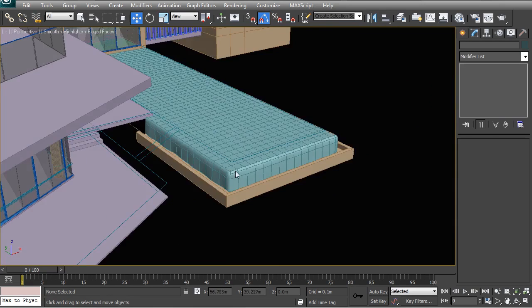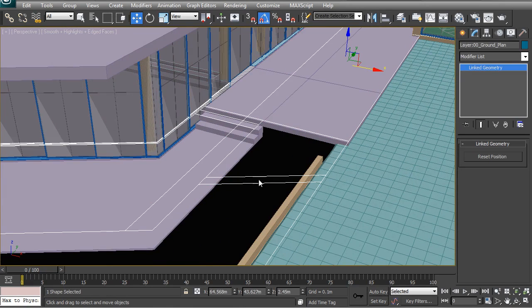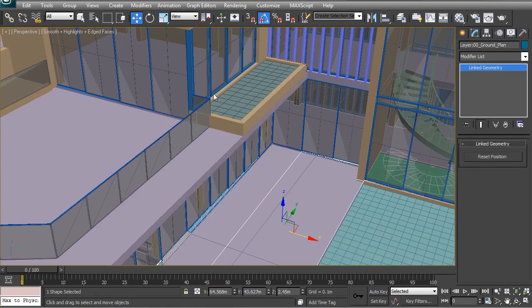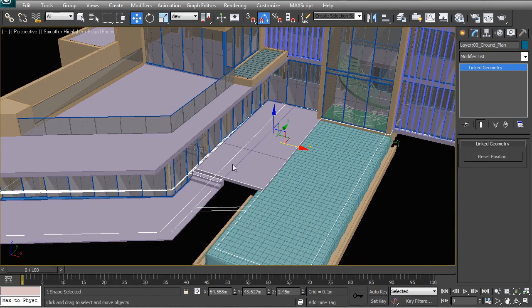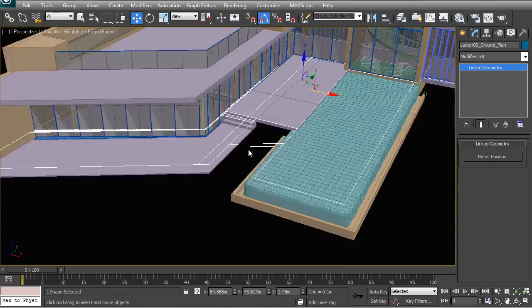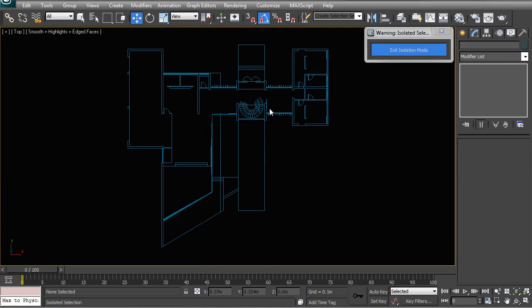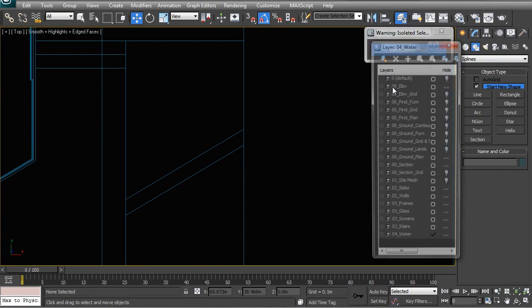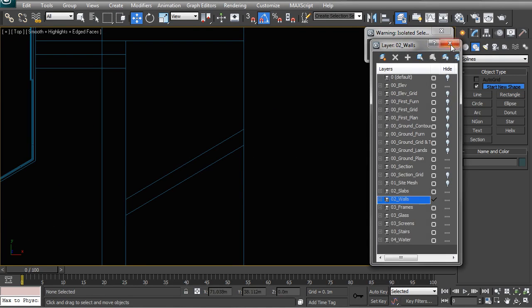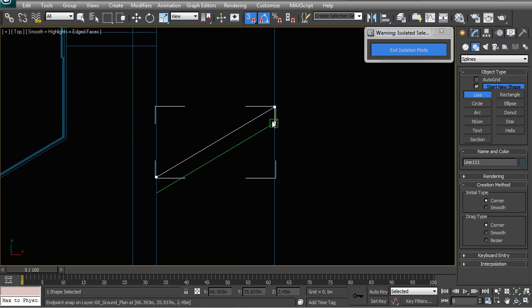Next, what we want to do is to create this area over here. So namely, we're going to add a wall here and then a planter into this area. And note as well that we already have a planter up here, so we can start to use similar ways of treating these areas where we're going to have plants growing on our building. So I'm going to first of all just isolate this, and in my top view I'm going to start to draw some of these individual wall objects. Let me just choose walls as my current layer, and I'm going to now outline this object.